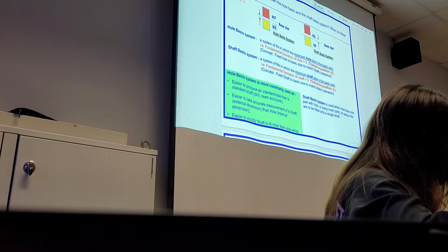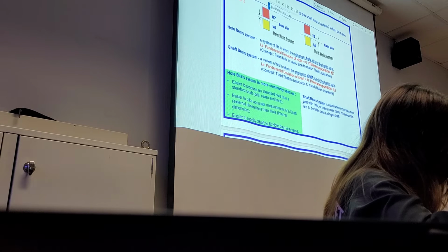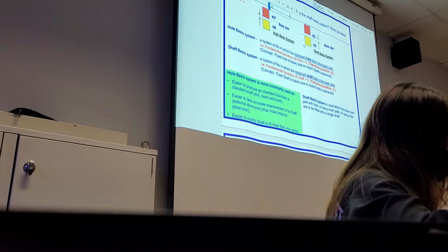So for example, H7 K6, what is the equivalent specification in the shaft basis system? Basically, it will be K7 H6.